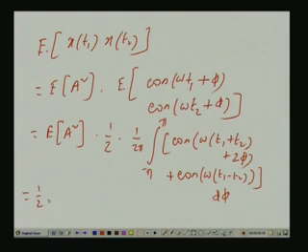So, this term can be brought outside the integral and will give rise to 2 pi, and 2 pi cancels. So, you simply get half E of A squared cosine omega t1 minus t2. So, if t1 and t2 are the same, say equal to t, then the cosine of this value becomes 1 because the argument is 0, and obviously the power in that case will be half times E of mod A squared, E of A squared. Okay. It can be easily generalized to the complex case.